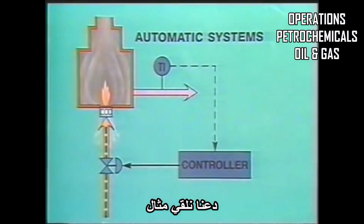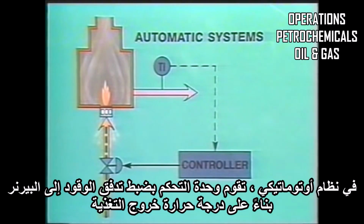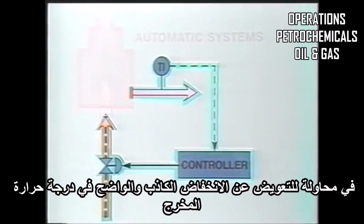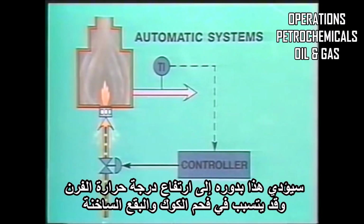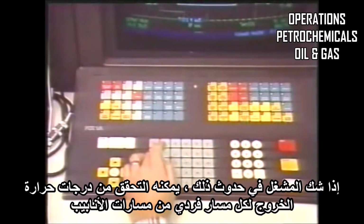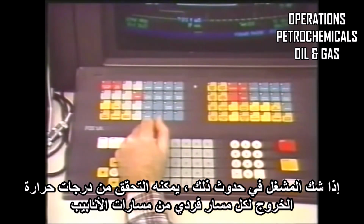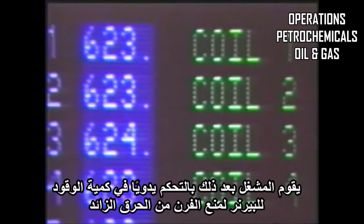Let's consider an example. In an automatic system, the controller adjusts the fuel flow to the burners based on the outlet temperature of the charge. Now, if the measuring or transmitting instrument sends out a faulty low temperature signal, the controller will automatically increase the flow of fuel to the burners, trying to compensate for the apparent decrease in outlet temperature. This, in turn, will cause the furnace to overheat and could cause coking in hot spots. If the operator suspects this is occurring, he can check the individual outlet temperatures for each pass of tubes. If these are above normal, this would indicate that the measuring or transmitting device has probably malfunctioned. The operator would then manually control the amount of fuel to the burners to prevent the furnace from overfiring.